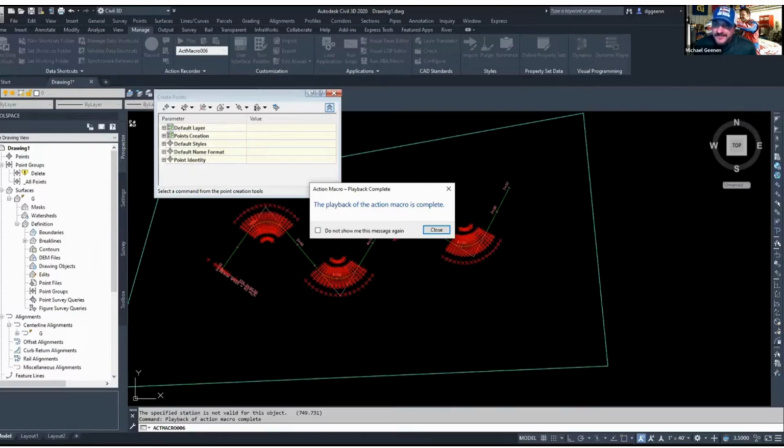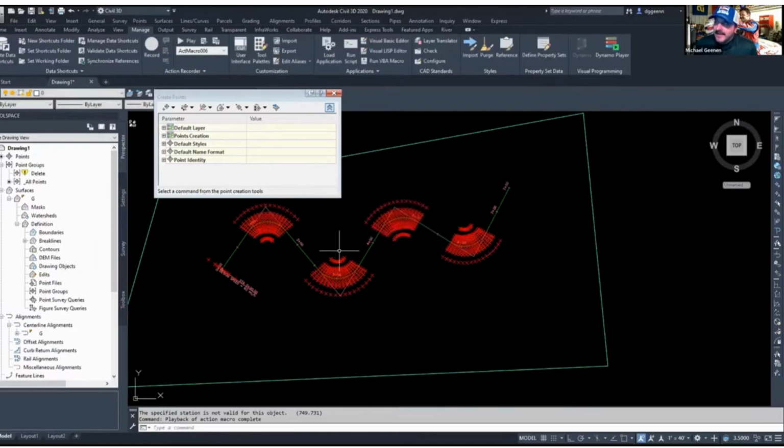I don't have to do that anymore. It saves a little bit of time and speeds things up a little, but more of the point is that there are ways to record macros in AutoCAD like you can in Excel. So any task you find yourself repeatedly doing, try to record a macro.